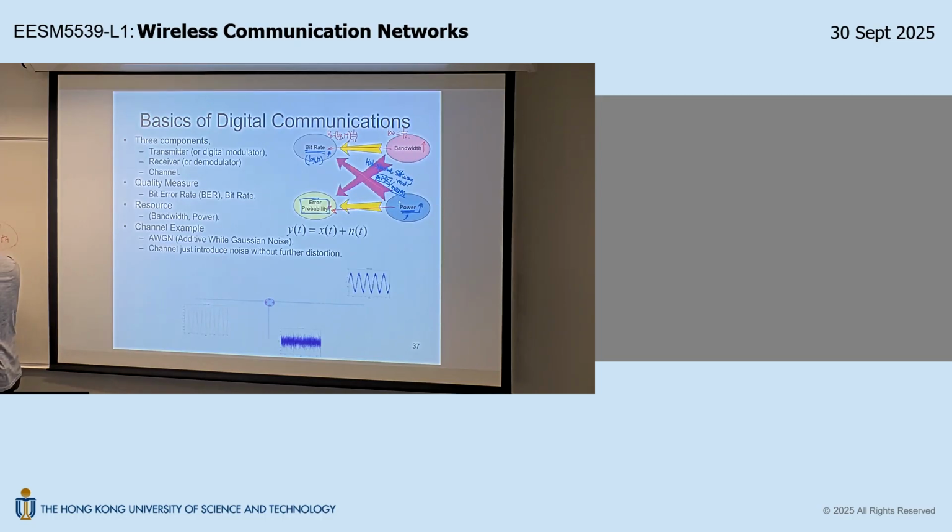Most of the time you stay at a low level, but sometimes you have an occasional high peak. This is a signal with high peak to average ratio. Okay? Peak to average ratio means the peak power divided by the average power. So it's a property of the waveform. When your waveform has a large peak to average ratio, you need higher power back off to avoid clipping.